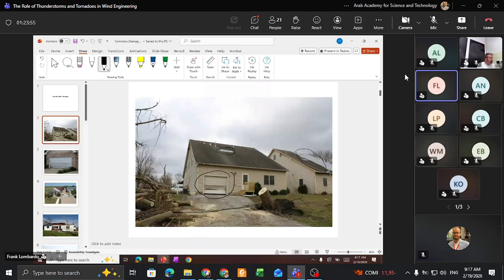We also talked about this with internal pressure. I have a couple of good examples of this, but think about it from an internal pressure standpoint: if air can get inside, if the wind can get inside, you have, again, that upward force on the inside of your roof. You also have maybe uplift on the roof. And so this area immediately above the garage door can tend to be an area where you see enhanced damage.